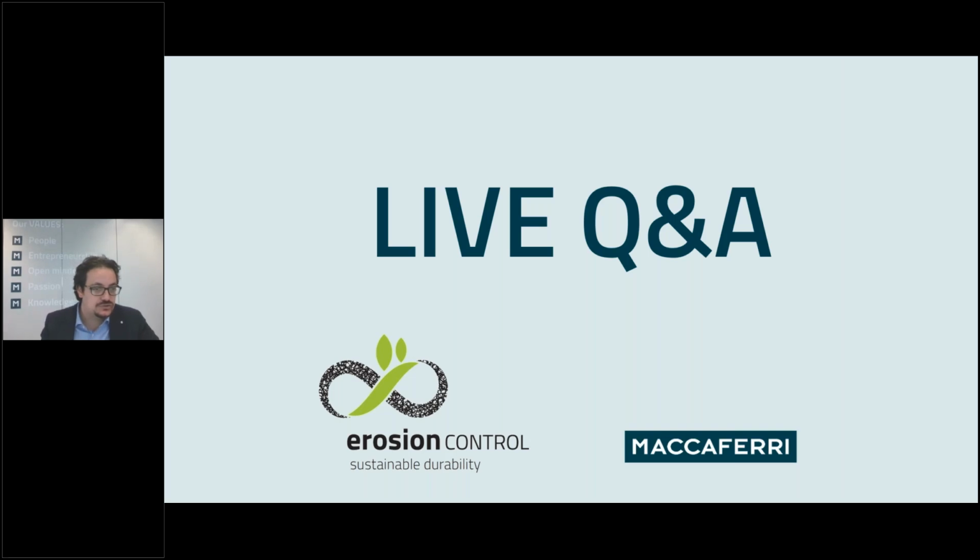Can you recommend a solution if vegetation growth is low? Depends, something that you have to evaluate. So typically with the reinforced geomat, you still have a protection of the soil loss due to the geomat itself. But of course, if you don't have a vegetation growing, the solution will be a little bit less effective in terms of erosion control. By the way, if it takes more time, it's not an issue, because in the meantime it will be the geomat that takes care of the soil loss.